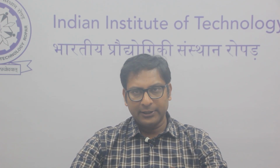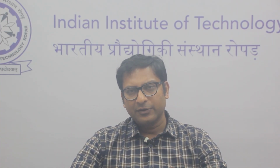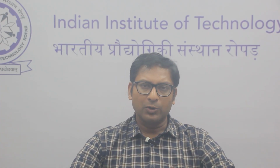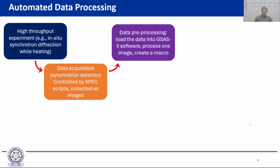And then as you are doing the data acquisition, this entire process is being controlled by some sort of a script which is being used to control the instrumentation part. In this specific example, you might think that the data is being collected as images because you have maybe a CCD camera at the end which is acting like your detector. Once you have acquired the data, the next step is to do some sort of data pre-processing. The raw data files that you get directly from the detector are not really usable. So you have to do some sort of pre-processing to convert the raw data into usable data.